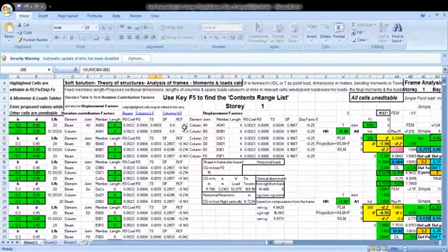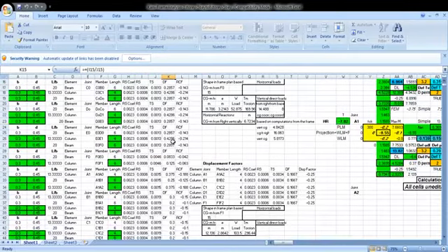Now distribution factor. That's the point. Now let's say what this factor is. This is I10, relative stiffness, over J10, total stiffness. Relative stiffness, this divided by this. What is this? Total stiffness, sum of I10. So this we divided by this, and we get this answer. And this works for everywhere.